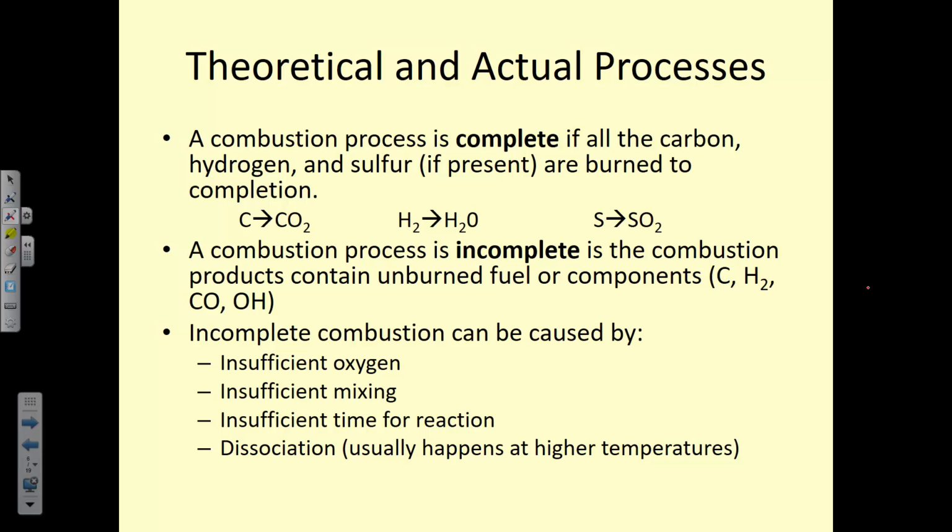Okay, so let's talk about the difference between a theoretical and an actual process. In theory, every combustion process is complete, that we have this stoichiometric amount of air. We'll talk about that term in a minute. And that it's a perfect scenario where all of our carbon is combined with oxygen to become carbon dioxide.